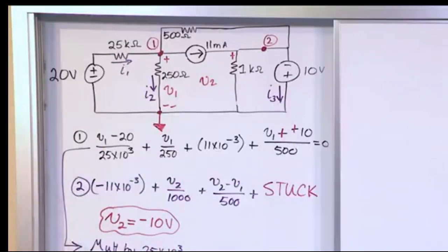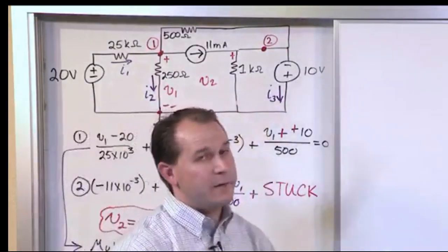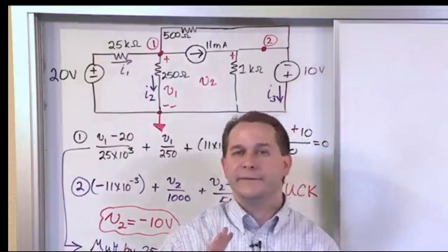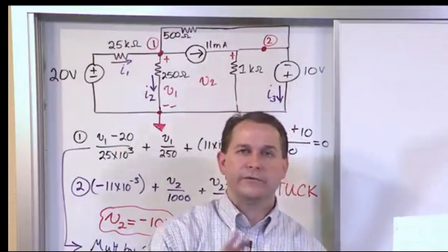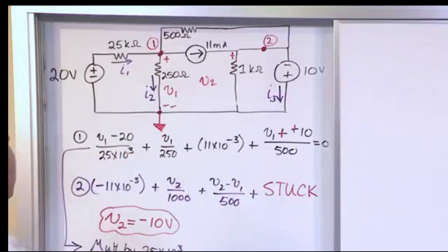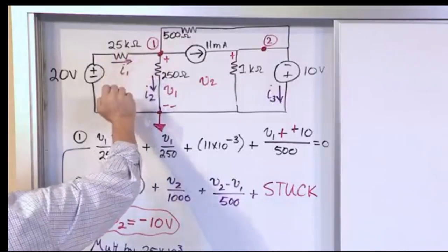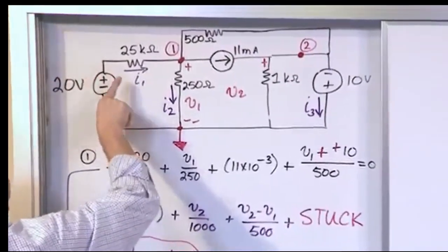So you've solved the node voltage, you know V1 and V2. Right? How do we go about finding these currents? Well, that's just going to amount to a little bit of subtraction and figuring out what the voltage is across the resistor elements divided by R is going to give us the currents. So as an example, let's look at I sub 1. How do we find I sub 1? Well, it's drawn as if it's going this way.